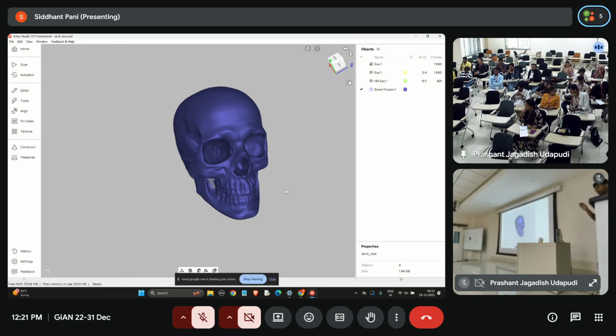So the cameras won't be able to capture the deviation in those small grids. And that is the core of how this thing generates the shape. It captures the deviation of what it is projecting from three different cameras here. If it's not able to capture that deviation, then it cannot do the mathematics to reconstruct it. So not for internal low lit environments.